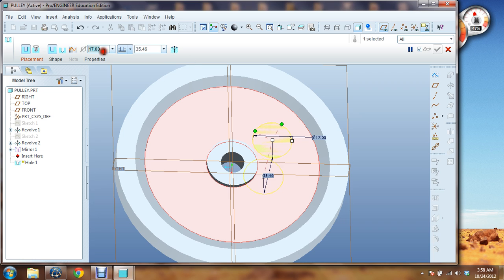So right up here we have our option to define the diameter of this hole. I can call it 5 if I want, or I could also click it on here and I can drag it around. You notice most features are like that. There are multiple places to define it. It doesn't really matter what your preference is, just define it.